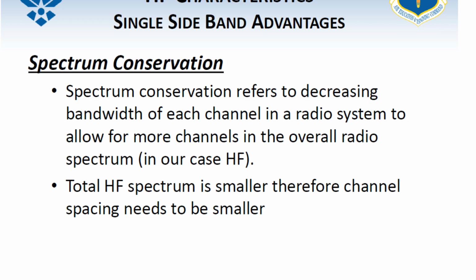All right, can y'all see this? Yes, sir. All right, this is CPA. You're going to learn about this more tomorrow when we do our lecture. But what he's talking about right now, you guys see that USB right there? I can change it to LSB. Yes. And look at that. See, it switches sides. And they're the same frequency, but you'll notice what he's talking about there. If we look at the lower sideband one, and they're the exact same frequency, it takes up 6.7817, 6.7847, 6.7853, and 6.7883. So that's why you're able to have them on the same frequency, because they're not truly on the same frequency.